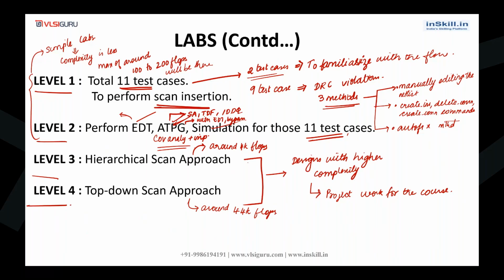We'll also explore some violations like tracing violations. And simulations, as I told, theory and practicals will be done simultaneously. Whatever I told earlier: need of simulation, what is simulation, flow of simulation, serial and parallel simulation, simulation mismatch debug steps, that is what we are going to cover here also. Analyzing the waveform, all those things.